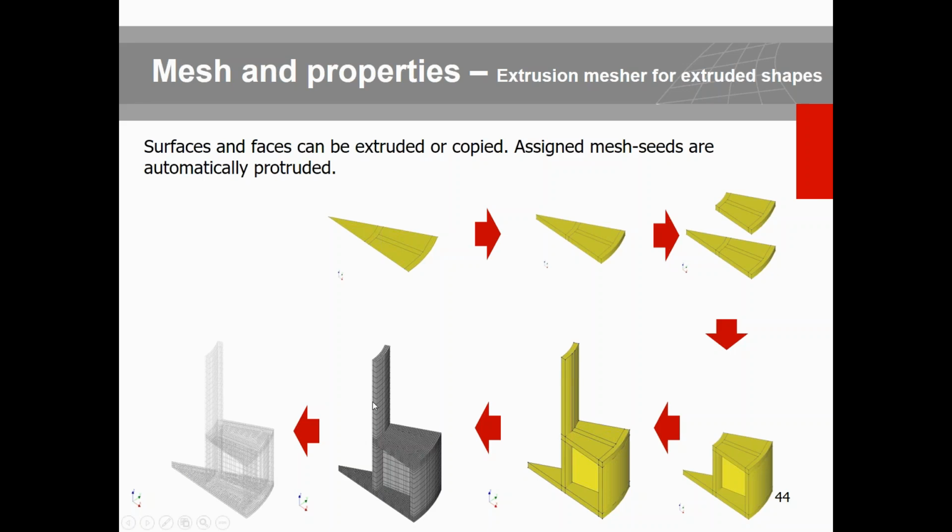In this particular case, I have a plate, and the model can be extruded based on, say, the thickness direction, and you can see how easily this model can be extruded. Since this geometry inherits this extrusion process, our mesh engine automatically uses the extrusion measure, and you have a very nice and uniform mesh distribution, or element distribution, in the extrusion direction.